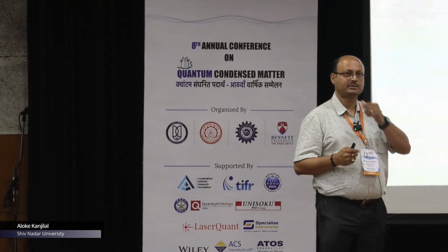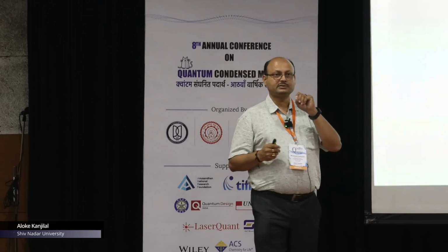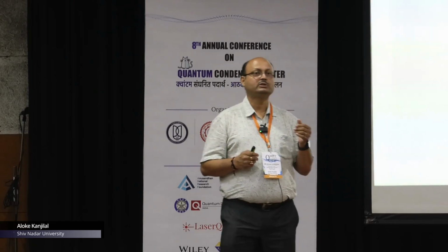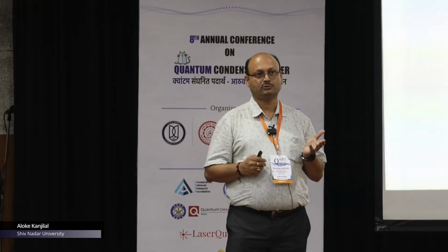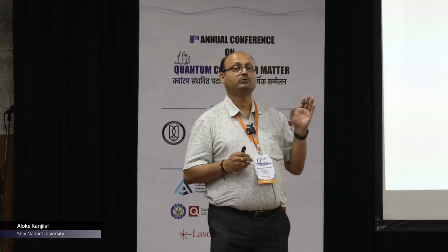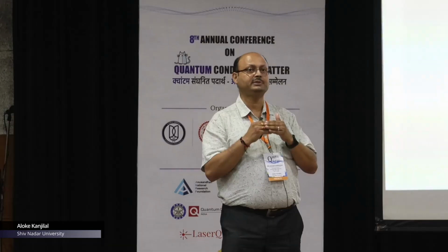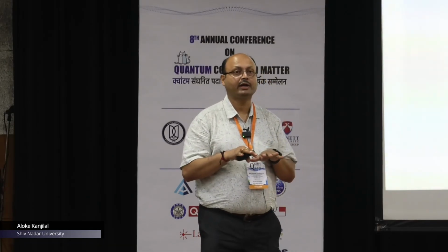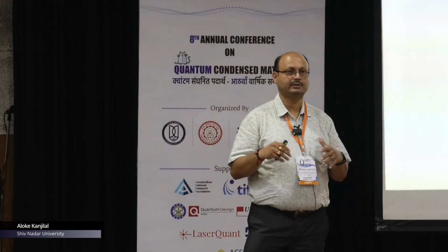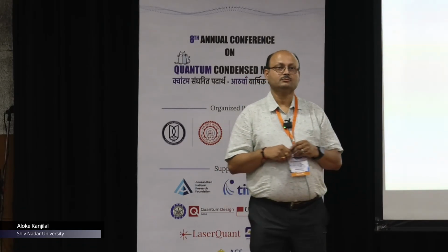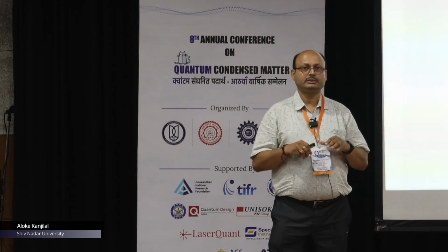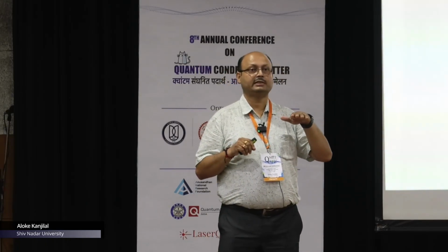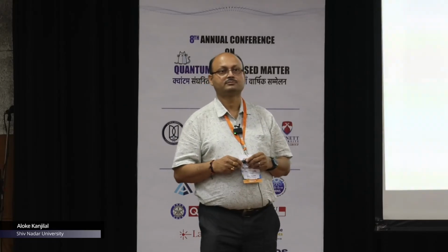That is definitely a good point that you picked up. Regarding the interfacial interaction, when we did XPS, we did not find any new phase formed. So there is no interaction at least, but we found strain formation. That means whenever hBN settles on the hafnium oxide surface, it modifies itself so that some kind of strain develops. Is the dispersion uniform or non-uniform? It is a uniform distribution definitely, but I cannot control the number of layers. That's the main issue. Okay, thank you.